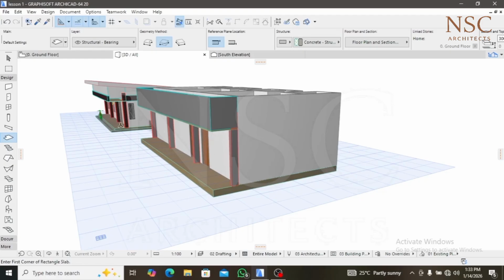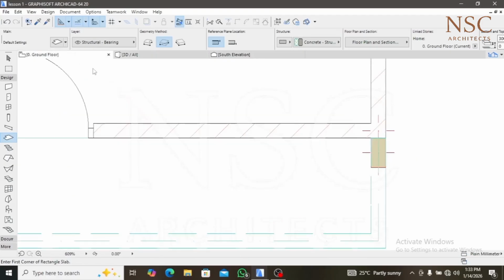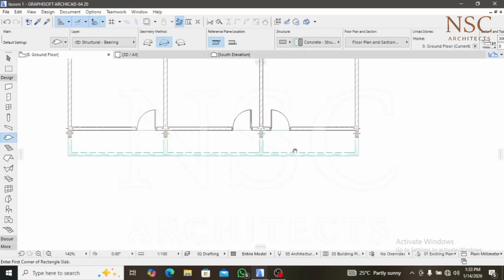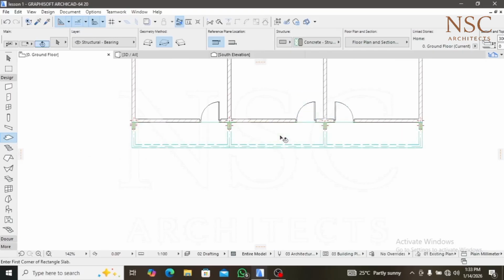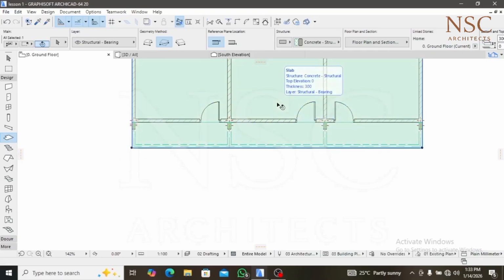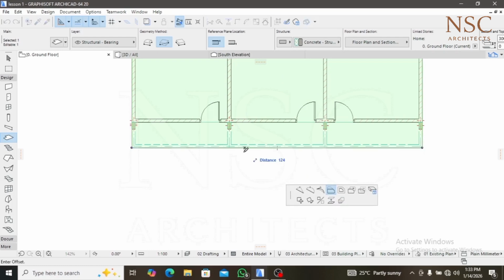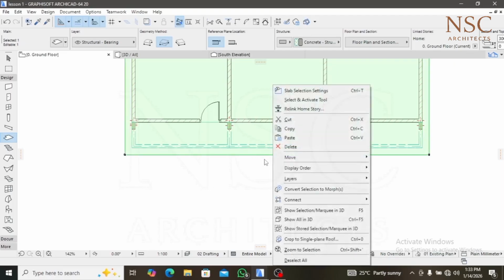Yeah, so before we go over to roof, before we do our roof, I want us to have a step down. Okay, you click on your main slab. So this is how I want to do the stairs. You come to this offset all edges. So click here, like bring it out. Click on your control button so that you have your plus appear there. Then click plus 300, like 300 now. So enter, boom.